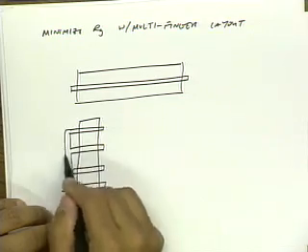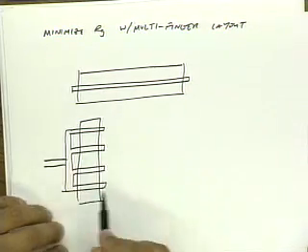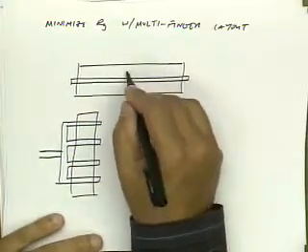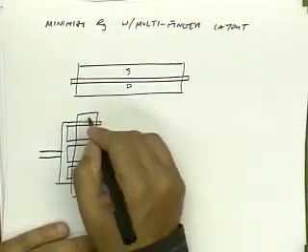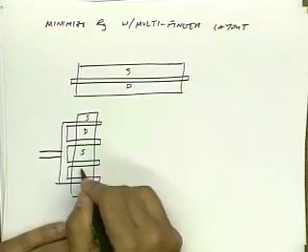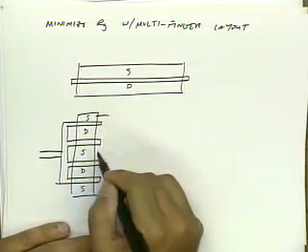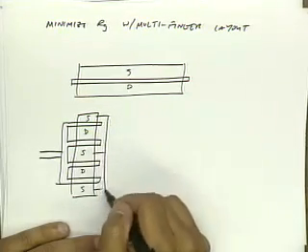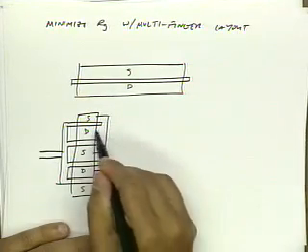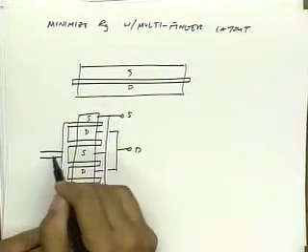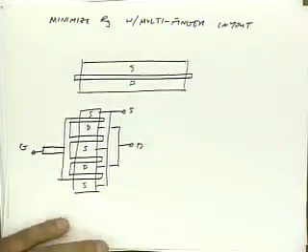And this is a standard trick in IC layout that you probably are familiar with. So here, if I have source and drain, over here I'm going to have source, drain, source, drain, source. And so I need to connect my sources together with some interconnect, and likewise my drain together. So this is my drain junction, this is my source junction, and this is my gate.